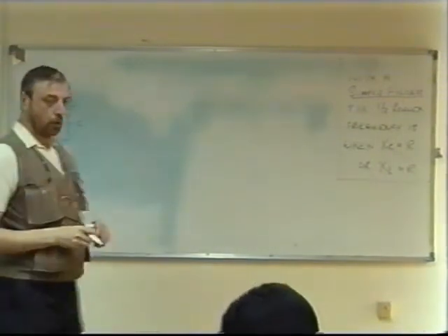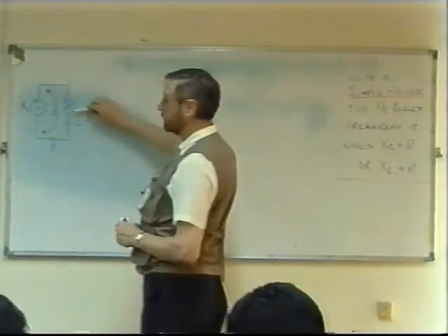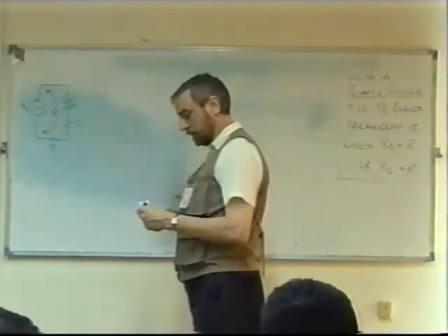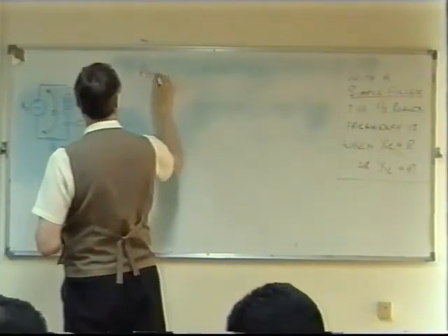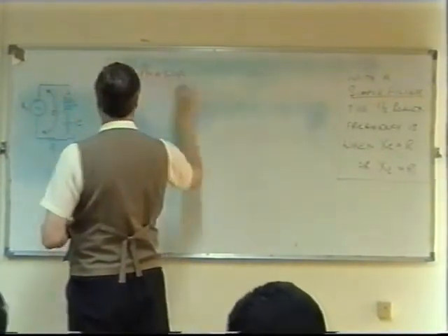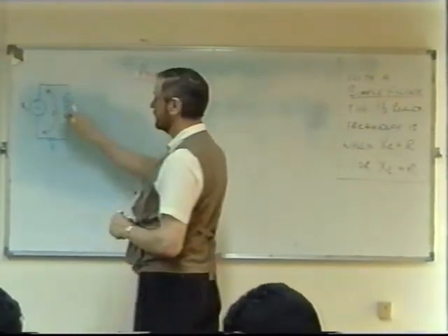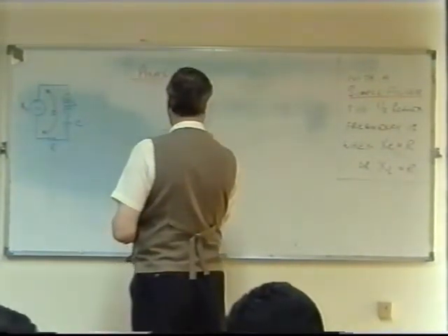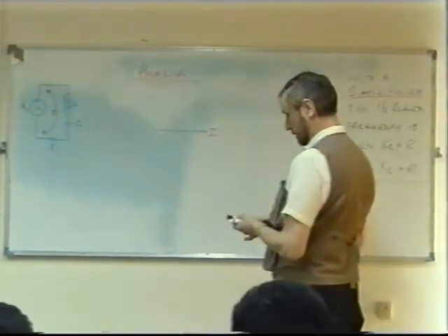What voltage is in the arm? Well, if we have a look at the circuit, depending on the value of current, we're going to get a voltage across the inductor, a voltage across the capacitor, and a voltage across the resistor. So the first thing we need to do is have a look at the phasor diagram. That's the first thing we must consider when we're looking at something like this. Beginning with the current, because the current is the same through all components, so that's our reference. And all we have to do is have a look at how the different voltages are across the different components.